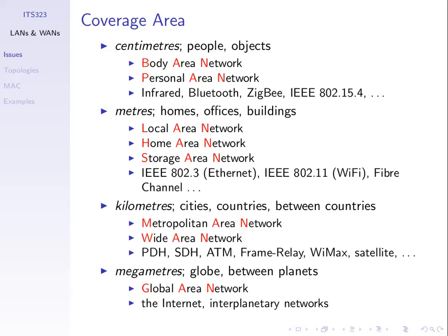The idea of multiple input, multiple output is that you transmit out multiple copies of your signal, one through each antenna. So with 3 antennas, for example, when you transmit your data, you really send 3 copies of that signal, one via each antenna. And for multiple input, there are 3 receive antennas, so they receive 3 different signals. And the idea is that those antennas are separated in space, a few centimetres apart.